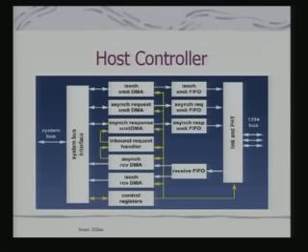So this interface is typically part of a PC, when the PC is one of the IEEE 1394 devices. It would be part of any other embedded system when that itself is participating in IEEE 1394. So typically you would expect a similar kind of controller even with your video camera, which is IEEE 1394 enabled. But a video camera may not have an extended interface for receiving data, because it is supposed to transmit the data in response to a request.